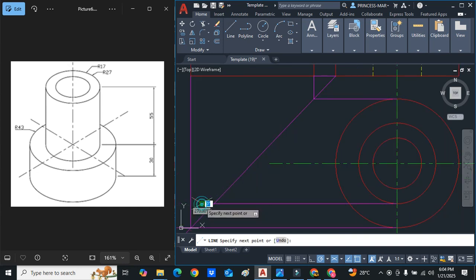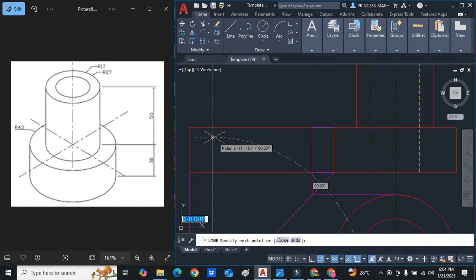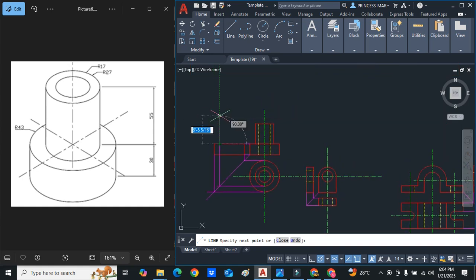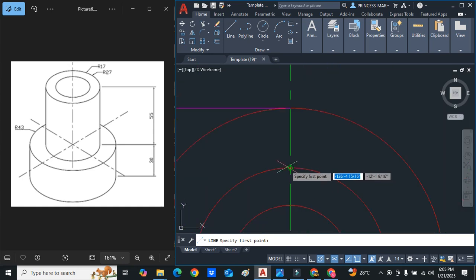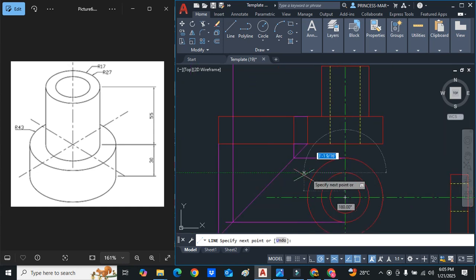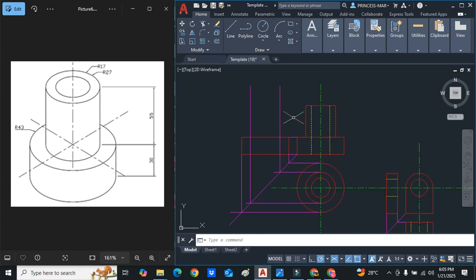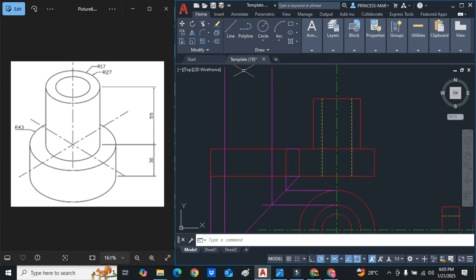So we project the line long, we bring it back to the 45, we come here, and we project upwards. Same thing here, project the circle across long, hit the 45, then we project the line upwards. So now, we just project across the top. Because we already have our measurements in the front view here, so we do not need to measure those parts again.